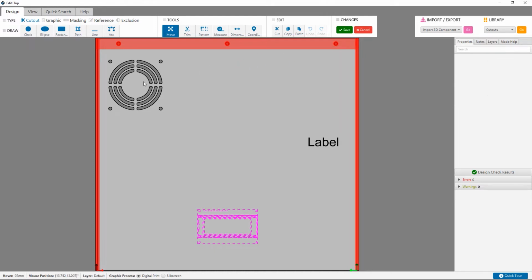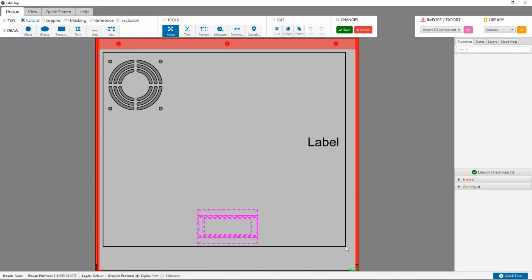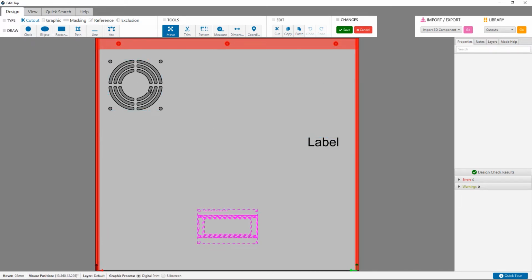The simplest way is through using Designer's Align and Distribute tools. In Protocase Designer 6, these are accessible by right-clicking with more than one object selected. Selecting multiple features is a pretty easy task. It can be done by clicking and dragging or by shift-clicking each item individually. For the alignment tool, we recommend shift-clicking each feature individually because they will be moved to align with the first feature that you have selected. For the Distribute tool, this is not as important because the features are distributed relative to whatever features are on the outside boundary. We will show how that works later.